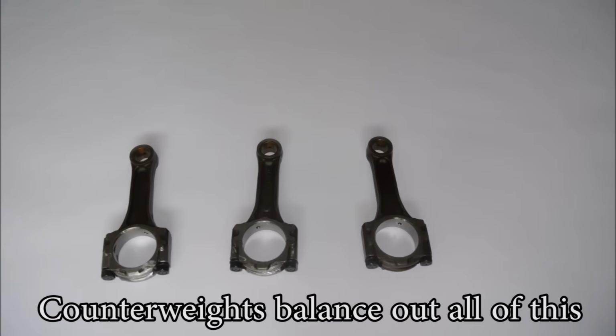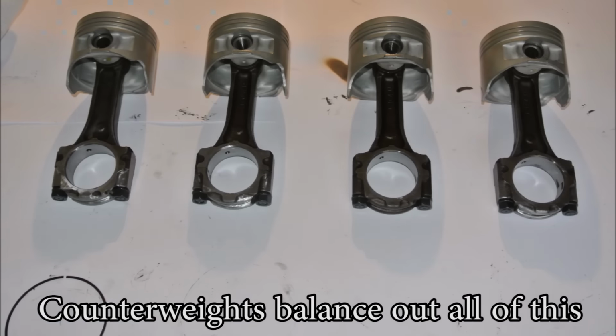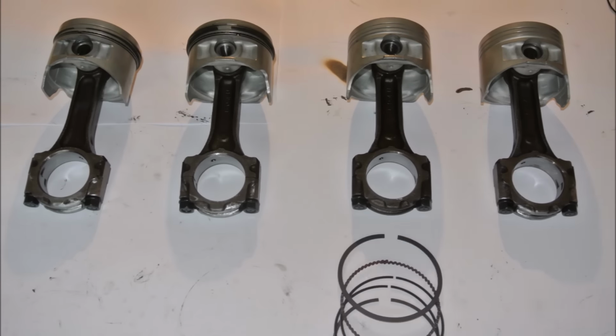Remember those crazy forces that we mentioned in the beginning of the video that the crankshaft is exposed to? Well, the counterweights have the very important task of balancing out these forces. Counterweights balance out the masses of the pistons and the conrods and the piston rings and the piston pin and their associated forces. Counterweights ensure that there's no vibration and that an engine runs smoothly for a very long time.